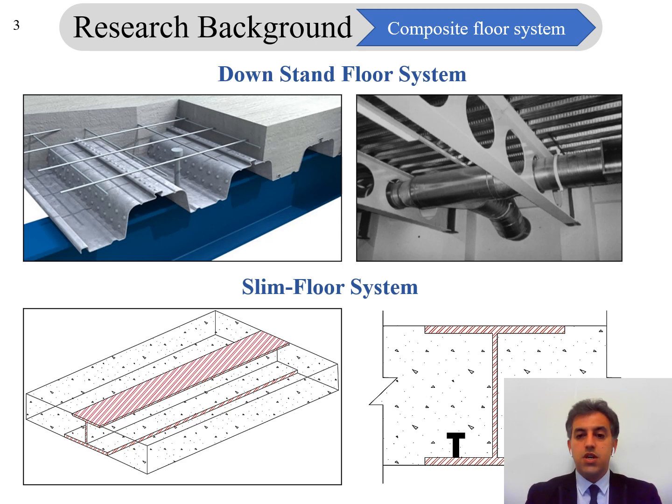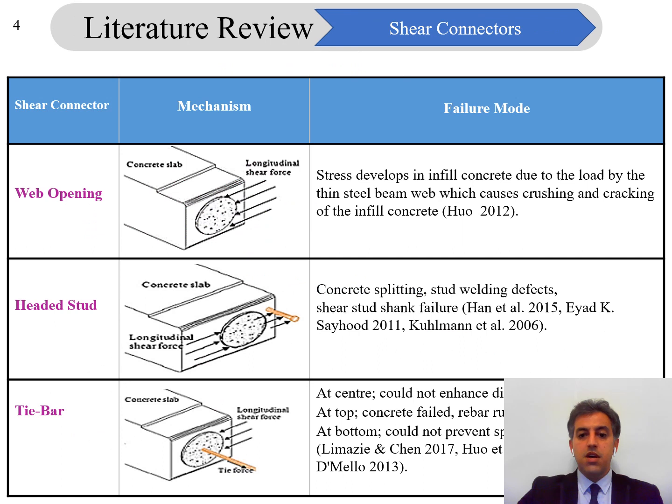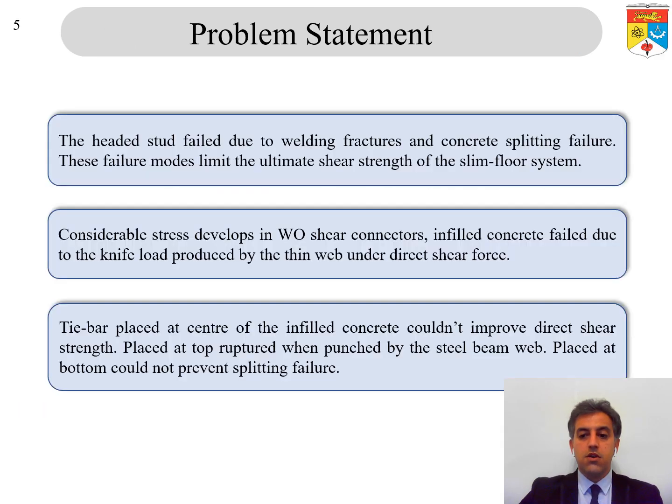Different types of shear connectors have been introduced and developed by other researchers for this system, which can be summarized as the web opening, headed stud, and the tie bar, where the tie bar is placed at the center, at the top, and at the bottom of the web opening shear connector to enhance the shear strength of those types of connectors.